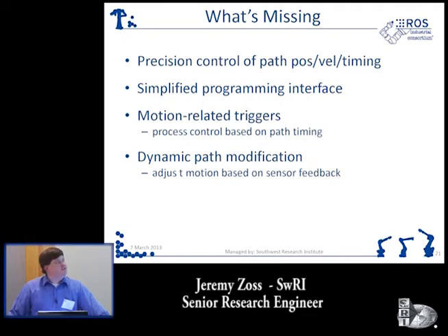ROS doesn't replace any current functionality of your existing robot controllers. It just supplements them. So all of those core capabilities that were in the robot controller before, you can still write a teach pendant program and run it on the robot controller. It's just going to be run for that robot, not in the ROS ecosystem. So I'm not meaning to say that you can't do it, you just can't do it from within ROS.